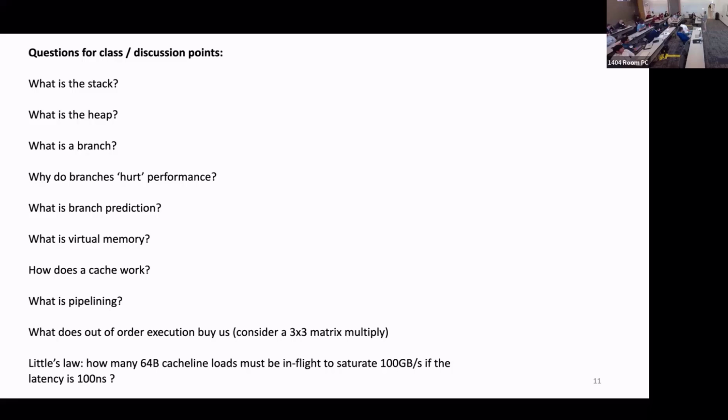Yeah, so these are called cache tags. They've got some number of lines and they've got basically the address of what they contain and whether it's valid or not, or what state it's in, right? They're called cache tags, yeah. And these are looked up. And then if you're writing to a cache, it'll stay in the cache till that cache line is flushed, and then it has to figure out, was this cache line modified? It needs to be written back to main memory. And if you have a multi-core processor where you have multiple cores trying to access each other's caches, then it's even more complicated.